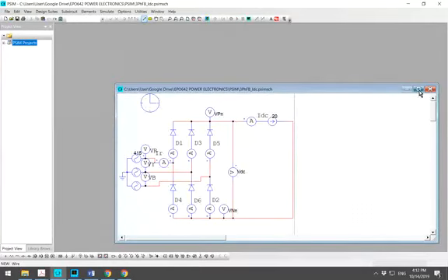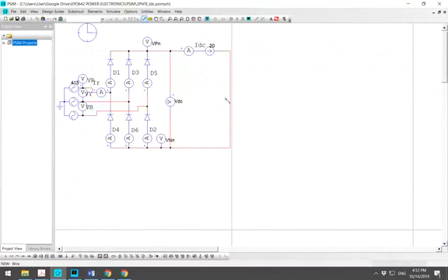Okay, so let's move on from the purely resistive load to the highly inductive R plus L load. In this case, we're going to look into the highly inductive load case, whereby the output current is ripple free. Therefore, in this simulation, we're going to replace the R plus L with a constant current IDC. Our objective here is to look at what will be the input current, the red phase input current.